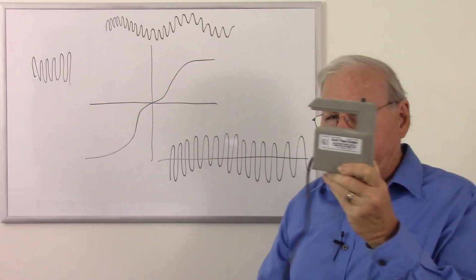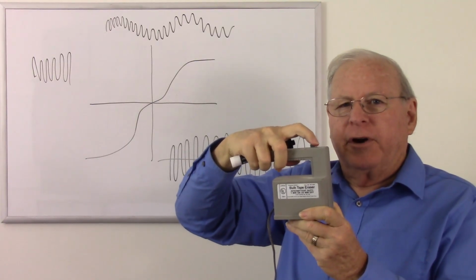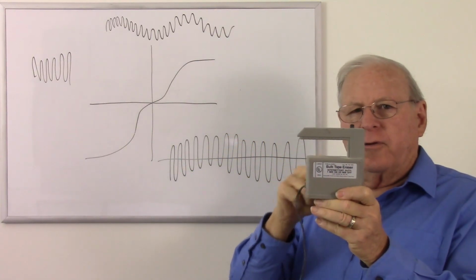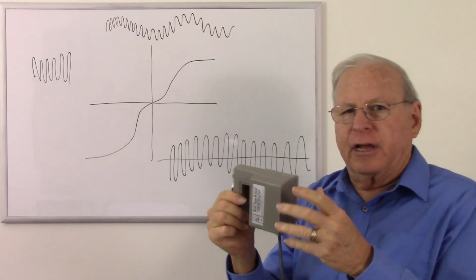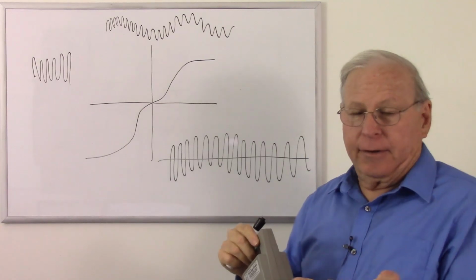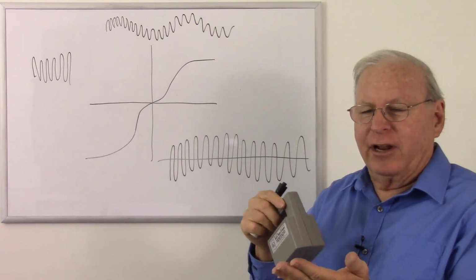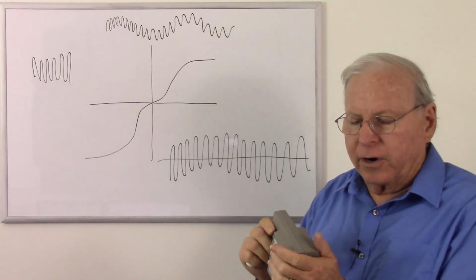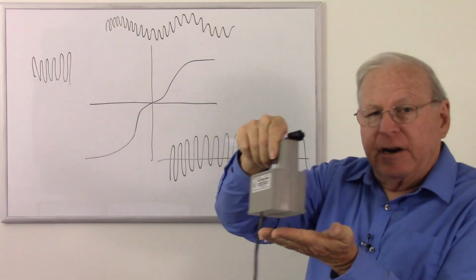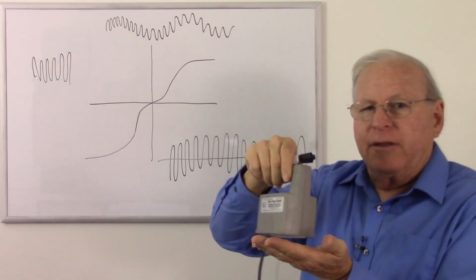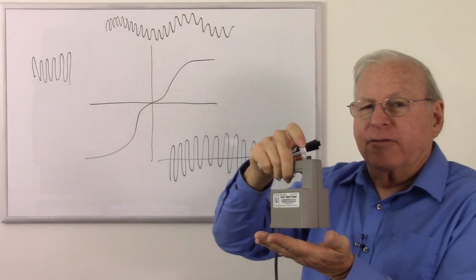But what this is, it's just got a power cord that plugs into the wall, a little momentary contact switch, and that just runs current through a big coil of wire here with a heavy iron core that's open at the bottom, so I have a strong magnetic field out the bottom here. And so to erase tape, I take a whole reel of tape, or later on floppy disks, or a compact cassette, whatever I was trying to erase, and I put this against that, and I move it around to get that magnetic field everywhere, so that it just scrambles up those domains, doing that while I'm holding this button, of course. And then I let go, well, it stayed magnetized one way or the other.